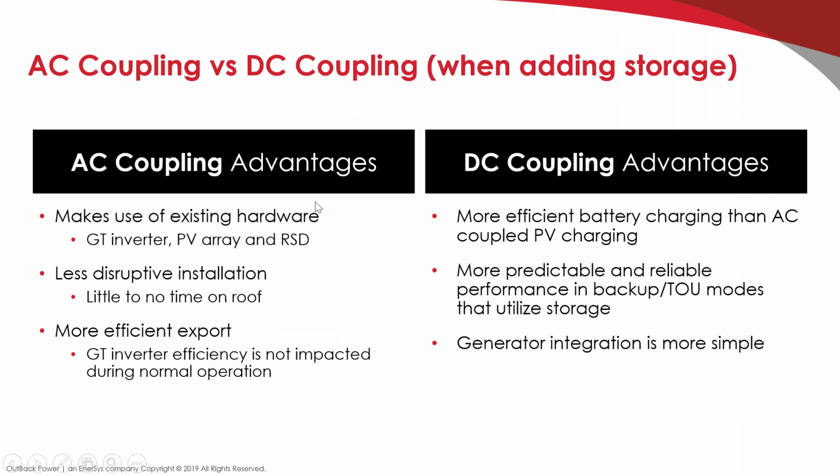So AC coupling, and this is true with anybody's AC coupled system, is never going to regulate the charging voltage to the batteries within a couple tenths of a volt. Nobody's solution does that. Now, with frequency watt, we do much better regulation, but it's still not going to be. And if you're only doing it a couple days, couple weeks a year, it's no big thing. But I would never recommend using AC coupling for daily cycling and charging of the batteries.